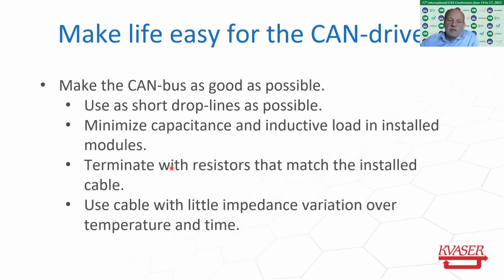You should also use a termination that matches the cable. The historic 120 ohm is perfect if the cable is 120 ohm. But if you use something like a Cat5 cable, a twisted pair, it has 100 ohm impedance, and in that case a 100 ohm terminator is a better choice than 120 ohm.